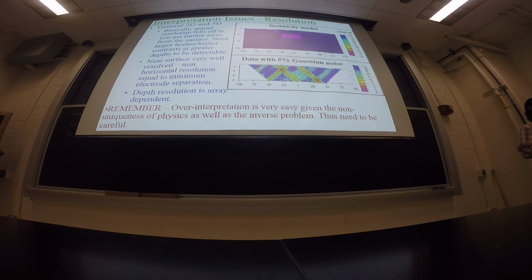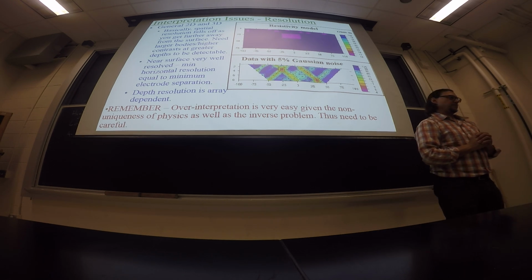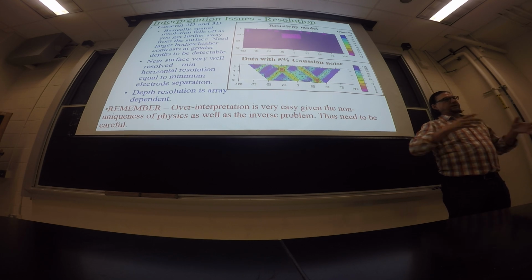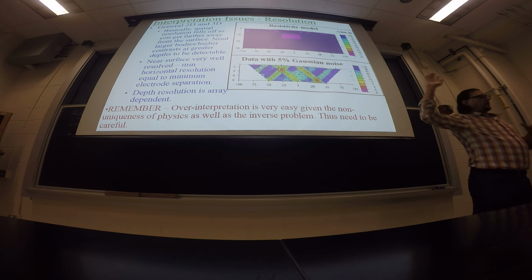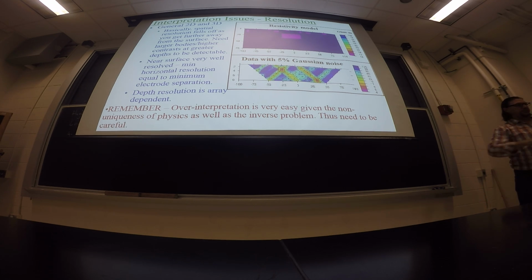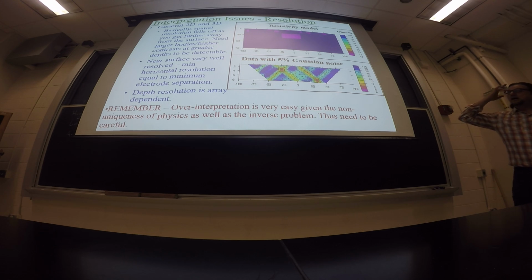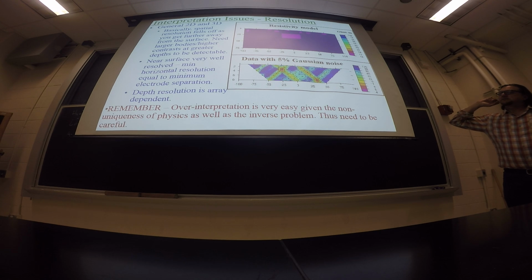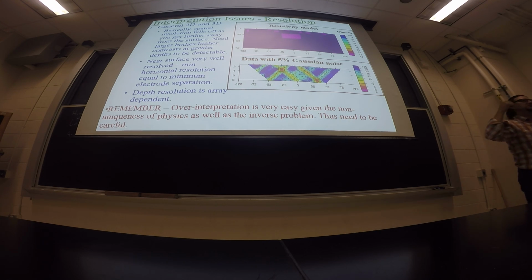There's electromagnetic variants of that called magnetotellurics and controlled source electromagnetics, which are related to this but give much deeper penetration, with much less hassle than spreading wires out on the surface. Engineering, hazardous waste site assessment: DC resistivity is used a lot for that, or for mapping old dumps and landfills.